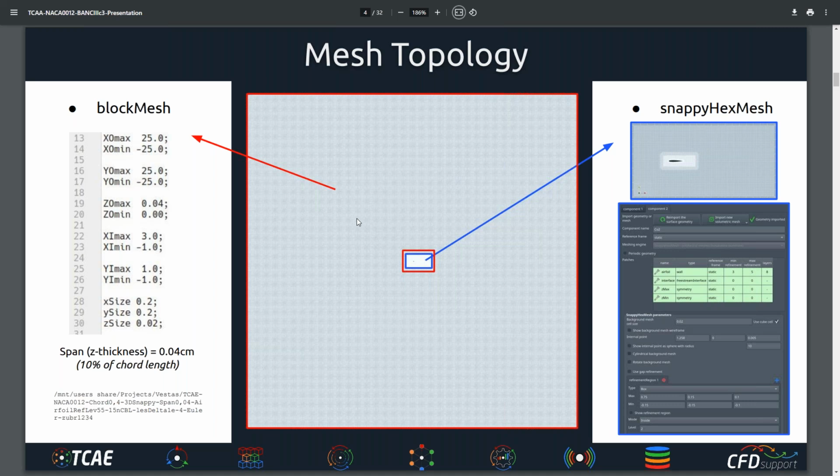Here we have just a cutoff of the span where we can apply the periodicities or symmetry boundary condition depending on the application. And here to achieve the automated meshing for the several types of airfoils, it is also prepared for adding serrations for optimization of the acoustics on the airfoils.